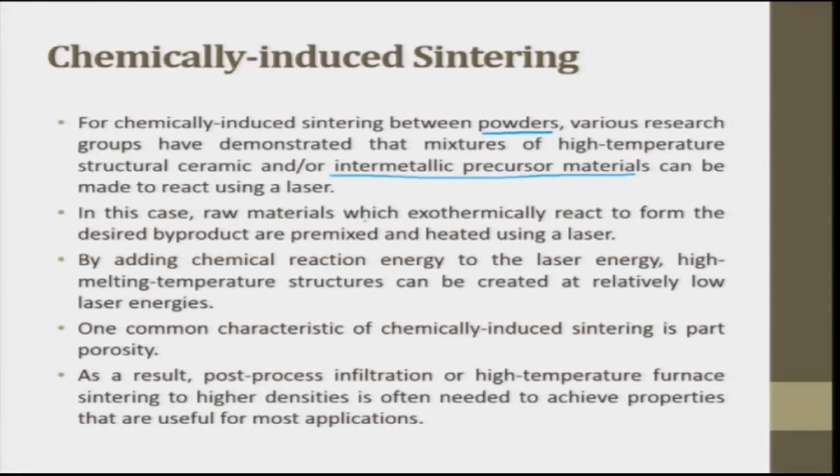In this case, raw materials which react exothermically are used. Heat is released while the reaction happens, and this heat also can be used for binding if you are smart. So the raw materials are exothermically reactive to form the desired byproduct, pre-mixed, and heated using a laser. By adding chemical reaction energy to the laser energy, high melting temperature structures can be created at relatively low laser energies.